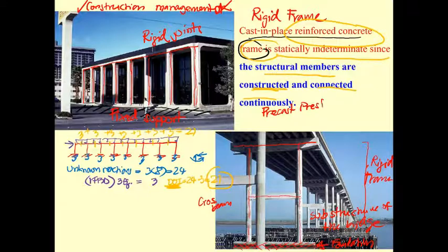During the construction of this substructure, in the factory you may have the precast pre-stressed concrete beam produced. At the same time, when the substructure is finished, the precast pre-stressed concrete beam will be shipped to the construction site, and you may use the crane to put the precast pre-stressed concrete beam into its position.